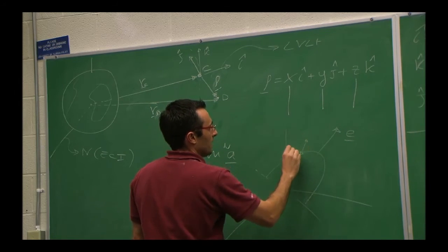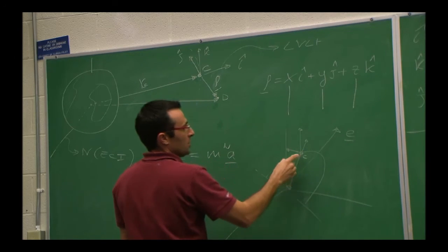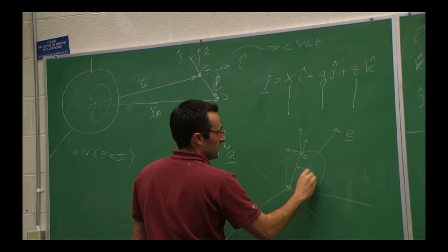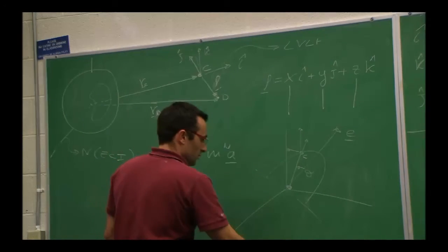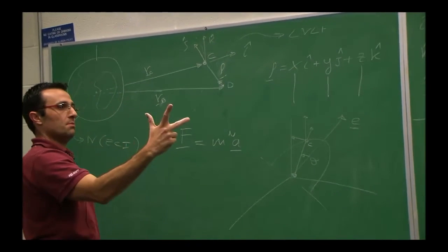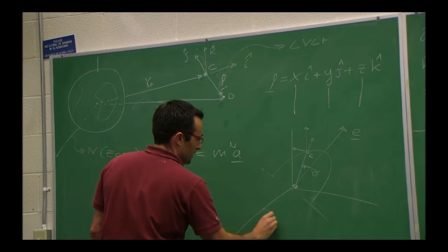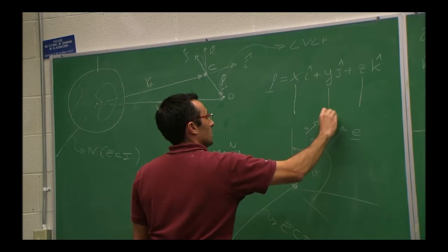I'm only looking at how this basis that is flying with the spacecraft, whose position is represented by, as you said, the true anomaly with respect to some line of apsides that we have defined, is rotating with respect to this one, ECI. This is ECI, and this is LVLH.